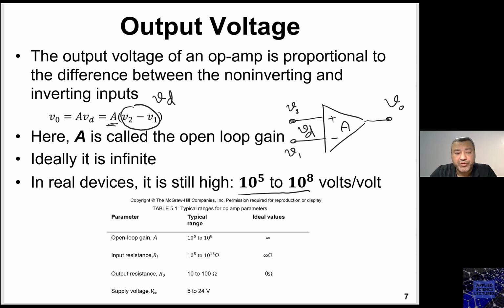Both of them. You can look at them as you're taking the difference, because here we have inside what's called the input resistance, Ri. So you're looking here at the difference between those two voltages. So the voltage drop across this Ri is basically the difference between V2 and V1. So this is your input. So both are inputs, and what comes out, V naught, is the output.